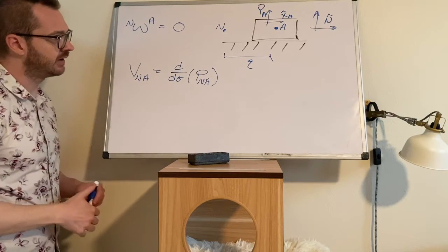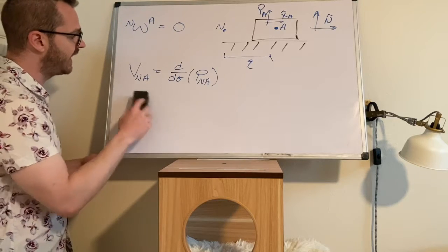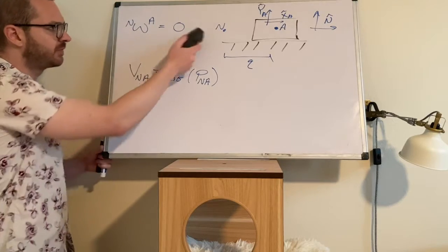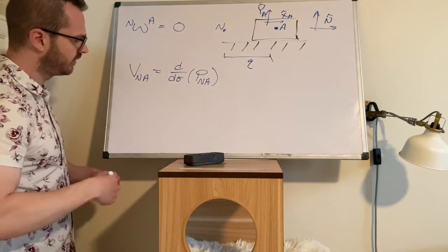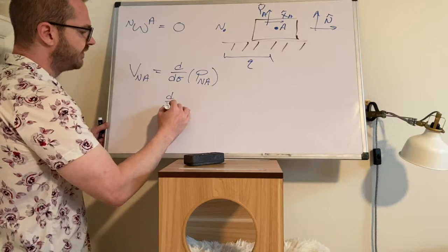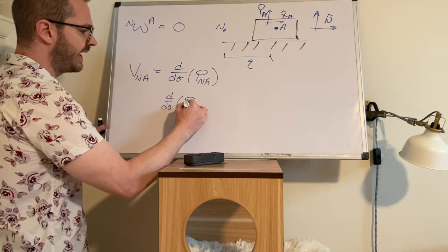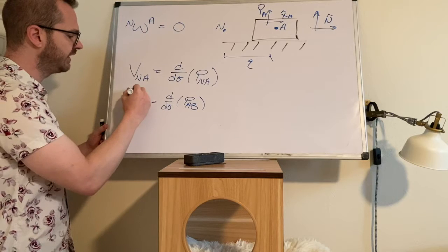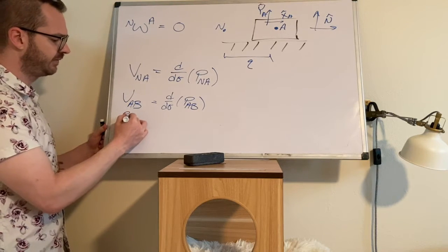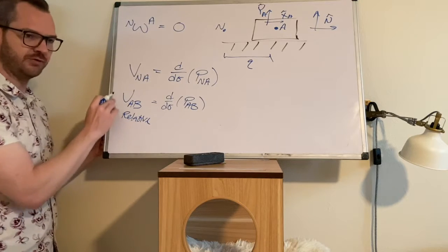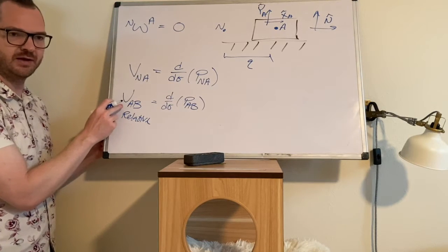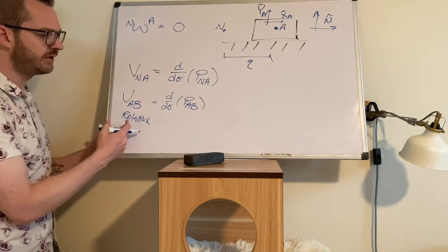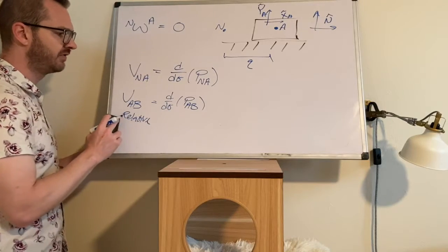Now N is a non-moving inertial point. So this, really what we're saying is we're talking about the absolute velocity of point A with respect to that non-moving point. Consider, we could take d/dt of position vectors like A to B. This position vector doesn't start at N, so what would this give us? This would give us the relative velocity between two points. This would be the velocity of B with respect to point A, but recognize that point A itself could be moving. We're going to do more difficult problems where we have to do things like this.